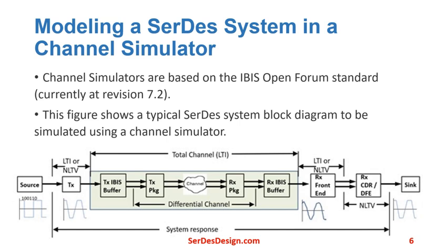Modeling the SerDes system in a channel simulator. Channel simulators are based on the IBIS Open Forum standard, currently at revision 7.2. This figure shows a typical SerDes system block diagram to be simulated using a channel simulator. This block diagram is generic for any channel simulator, but each tool has its specific way to represent this block diagram. The constituent parts of this SerDes system include the following: the IBIS-AMI model.